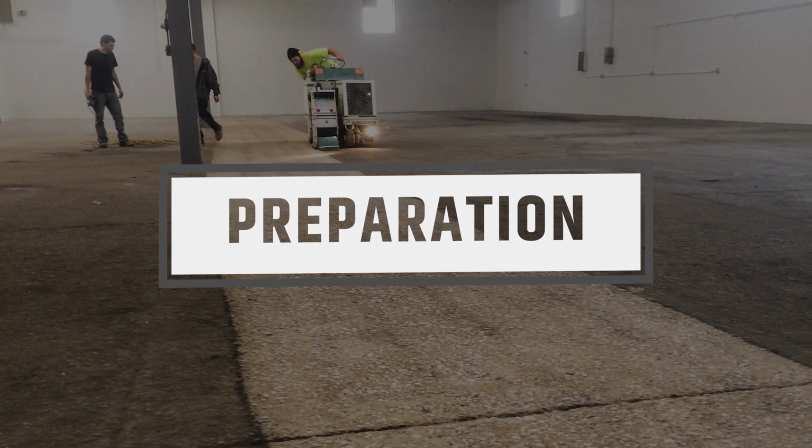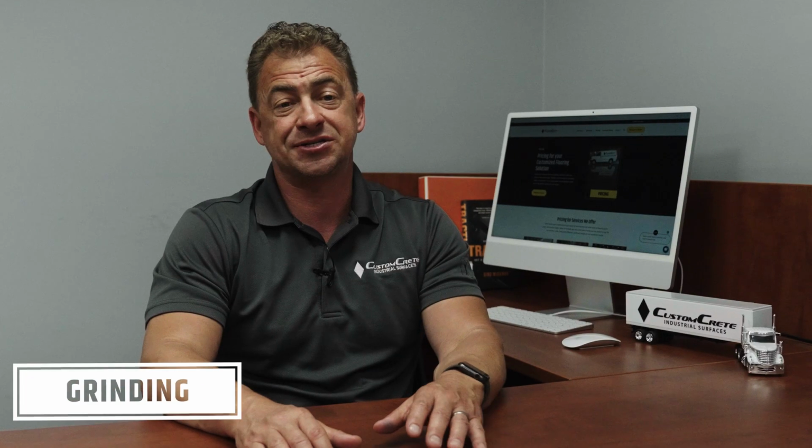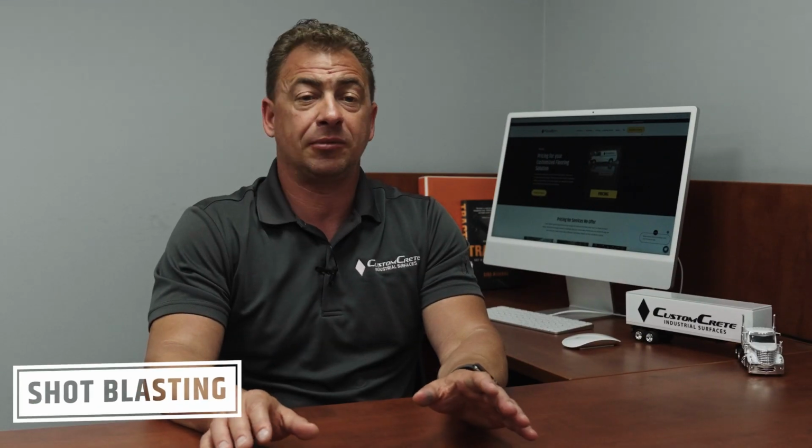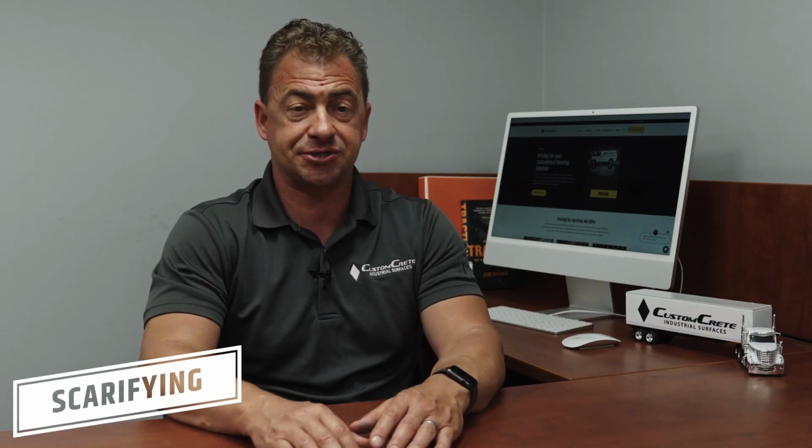Surface preparation. Typical preparation methods include grinding, shot blasting, and scarifying, each suited for different needs. Grinding is ideal for preparing surfaces for sealers and polishing. Shot blasting, commonly used before applying epoxy coatings. Scarifying produces very rough profiles suited for overlays or major restorations.